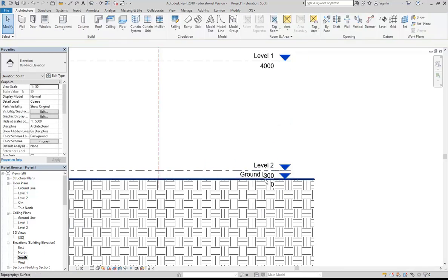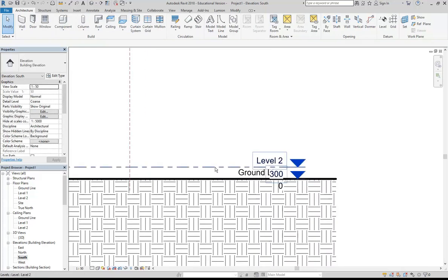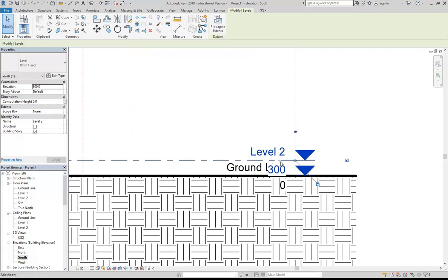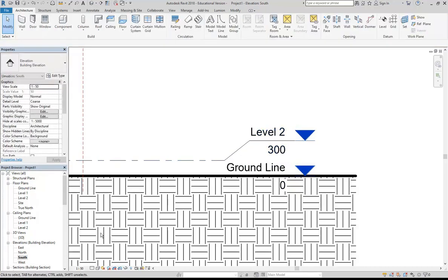And so I'm just pressing escape so I can select this level again now. And then I can show you the way of moving this text to adjust it a bit further. So after selecting that level, you get this little break symbol. So let's say add elbow. I'm going to click there, and then I can use the grip to bring this one up. And maybe, oh, so down here. Yeah, that's good. Because you should do that first, definitely.